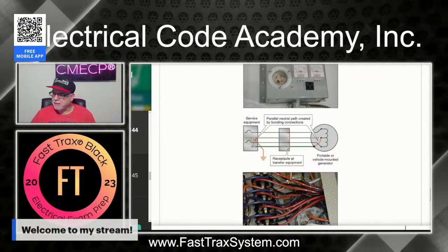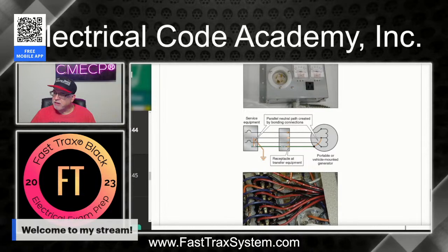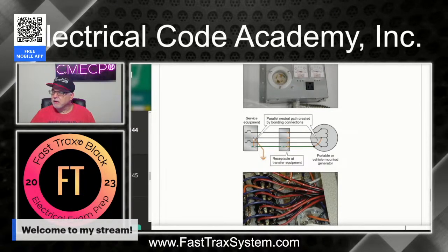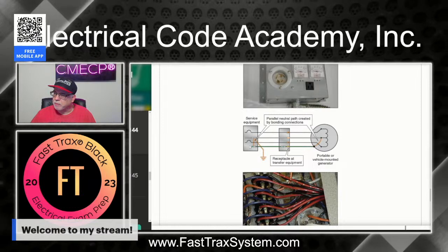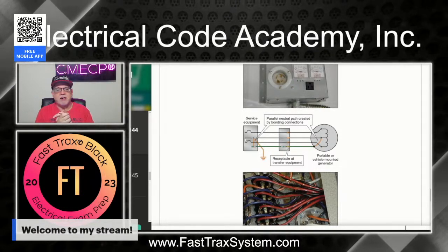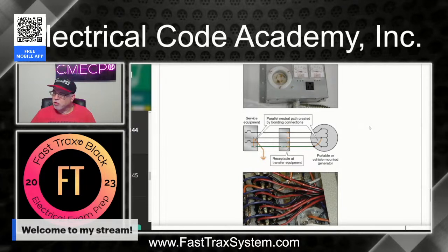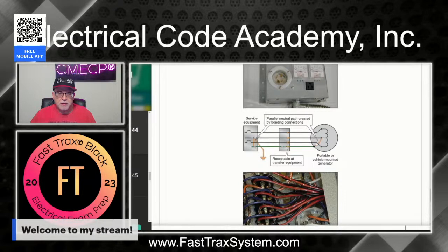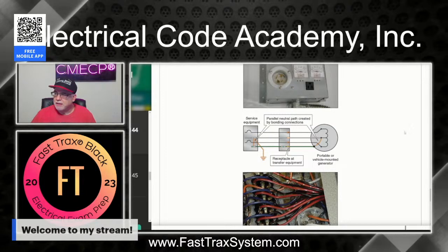All right? That means this neutral current, even in this service, when it's back to a service, can actually send neutral current back through, over through the winding, back through here, and then back on the equipment ground. Creates a loop. Okay? So it creates a very unsafe condition. Right? So either you're going to break it here at the generator, right? And if you do it here, then that's where typically you don't need to break it. You can use a solid bus type transfer equipment.